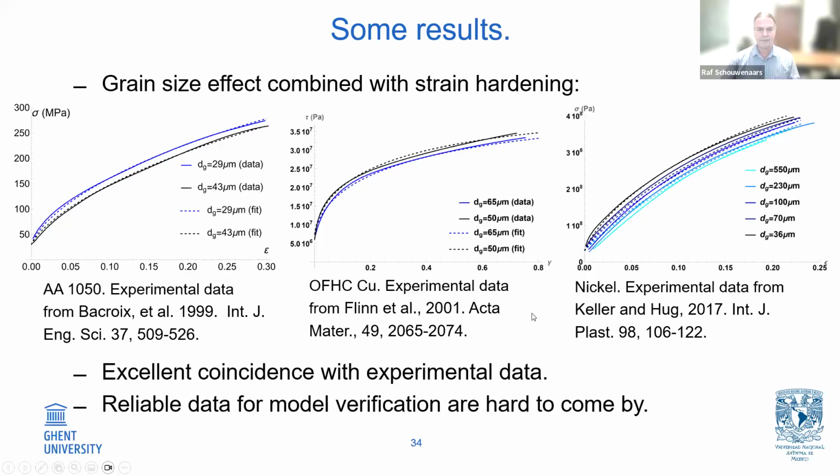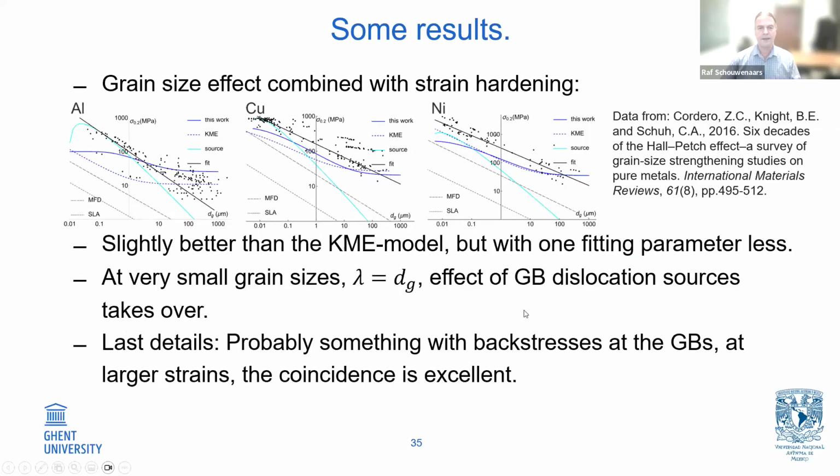So you can then look at the yield strength, and there are several graphs here. The black one is just a linear fitting. It's a log graph where we've got here 1 micrometer to 1000 micrometer, and here the shear stress, the yield stress from 10 to 10,000.